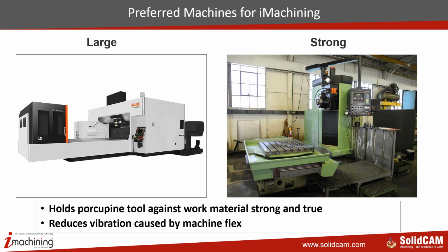What are the preferred machines for use with iMachining and insert cutters? Due to the large size of insert cutters, we want to use large and strong machines. These machines do a much better job holding the tool against the stock without machine flex. That can cause vibrations.